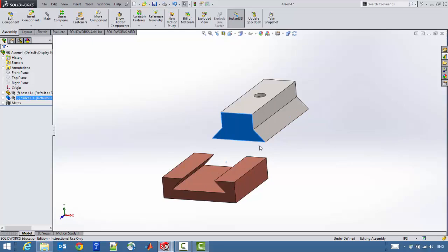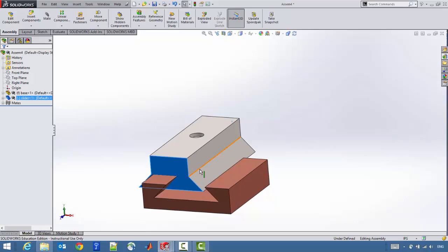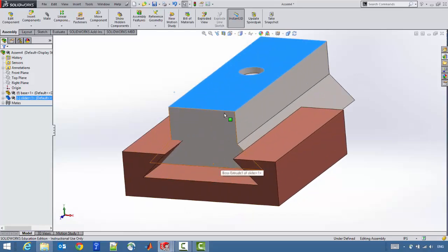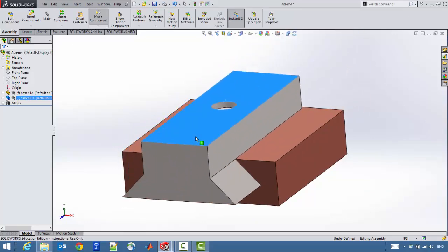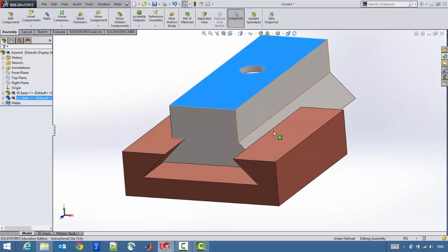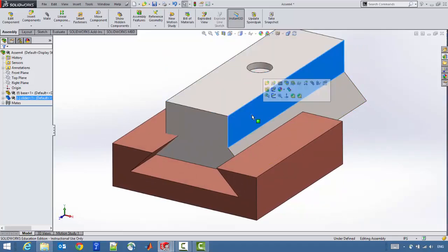Okay, so this speaks, of course, to the need of enforcing a set of additional constraints in order to be able to have our assembly as we intend. So probably the next order of business for these parts would be to enforce a constraint that would keep the slider in the middle of the base. Even if we were okay with this part not being restricted at all along the slide, at the very minimum, we certainly don't want it to go sideways. How would we do that? Well, different ways. We could, for example, enforce a distance between this face in here and that face there.